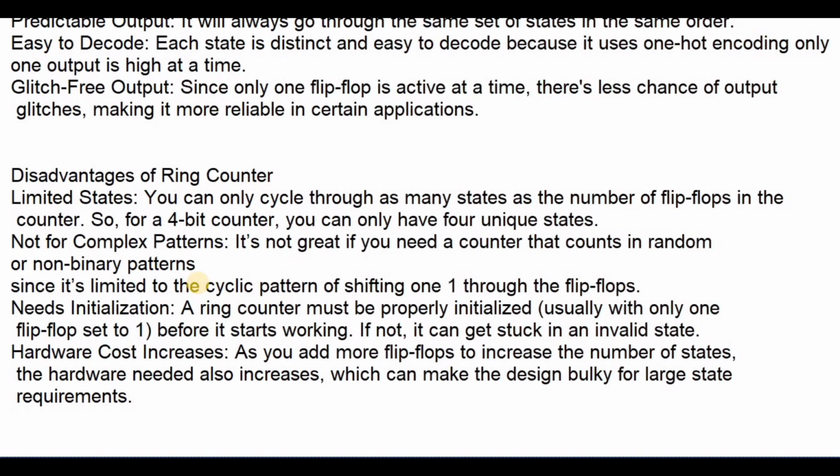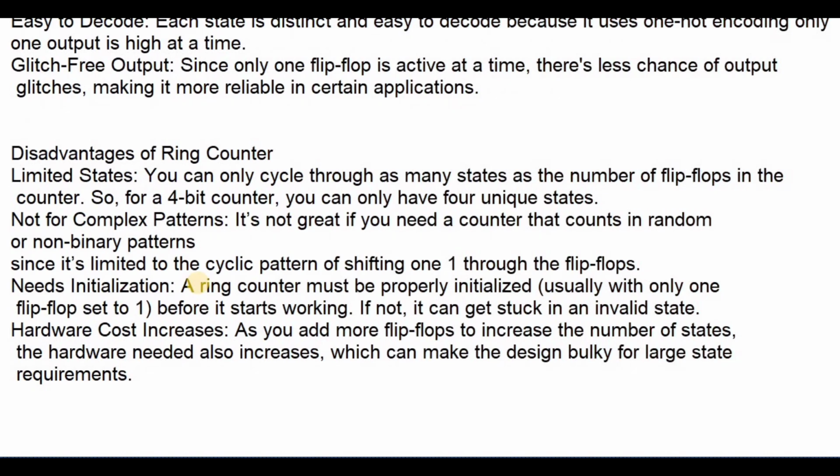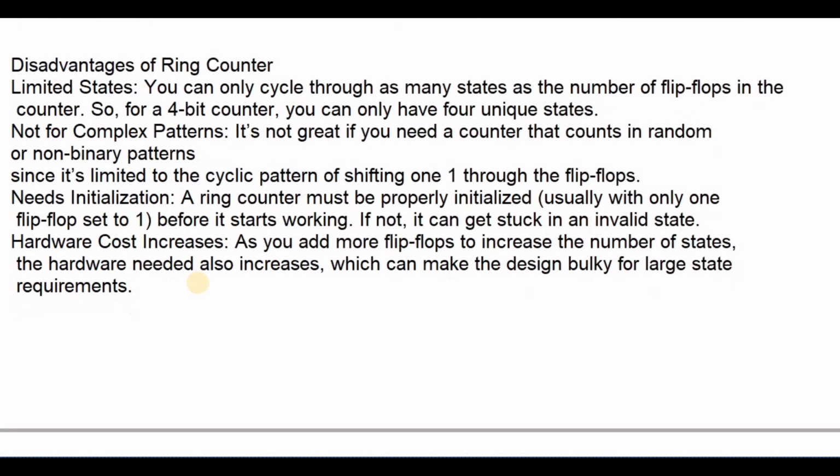So it is not great if you need a counter that counts in a random or non-binary pattern, since it is limited to a cyclic pattern of shifting one through the flip-flops, and it needs initialization, because with the help of preset only we are setting the initial state of one flip-flop to 1. Without preset we can't perform this ring counter. Next, hardware cost will increase. If you want to increase the number of states, the number of flip-flops will increase. So it becomes bulky if you require a large number of states. That is another disadvantage.